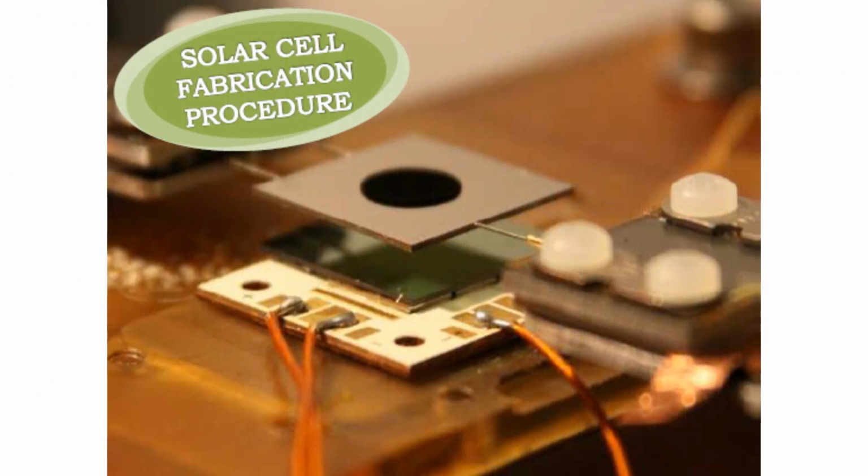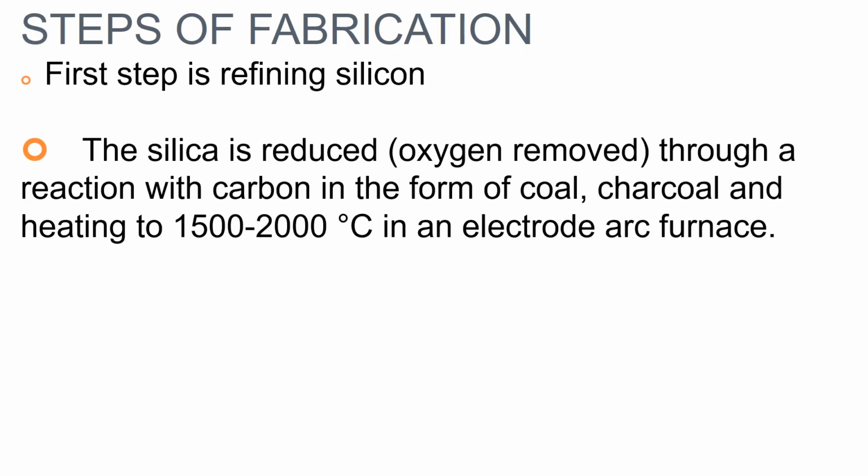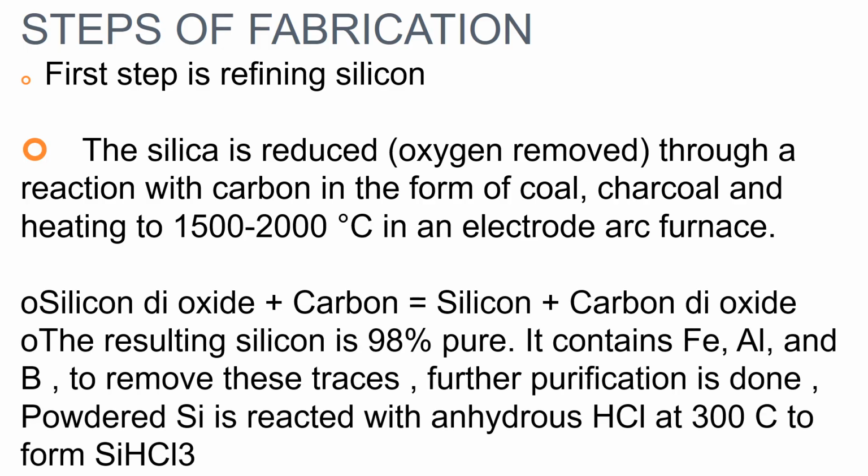Next we shall see briefly fabrication process of PV cell or solar cell. First step is refining silicon. The silica is reduced, that is oxygen removed, through a reaction with the carbon in the form of coal, charcoal, and heating to 1500 to 2000 degrees centigrade in an electrode arc furnace.